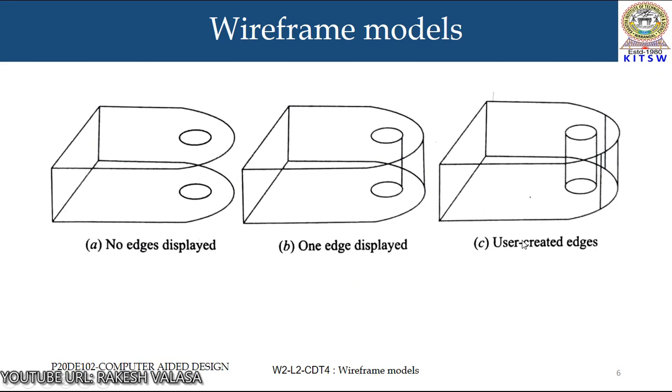In many cases, users add edges of the hole for appearance purpose at the drafting mode or may use a cylindrical surface to represent the hole, which introduces problems later during the model cleanup phase. In adding edges, inexperienced users tend to attempt to create tangent lines between the whole circles, which obviously does not work.